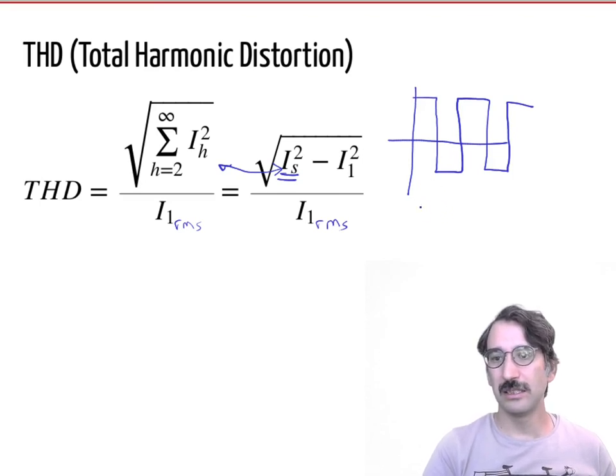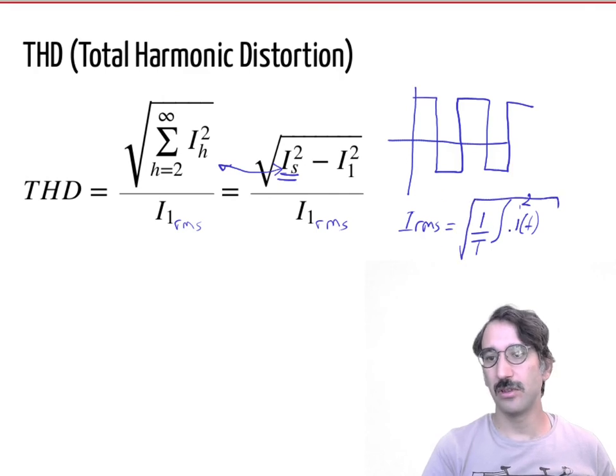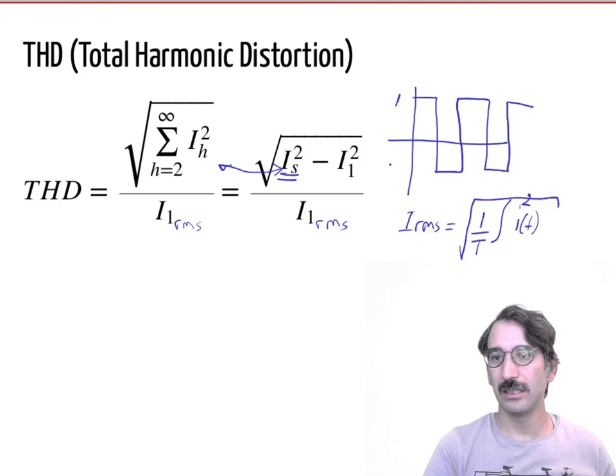Basically, what is it? The RMS is equal to, remember, the square of that waveform, and you integrate it, take the average, and then take the square root. So what will happen if this is 1 and this is minus 1? If you just take the square of that waveform, it will be a constant DC.